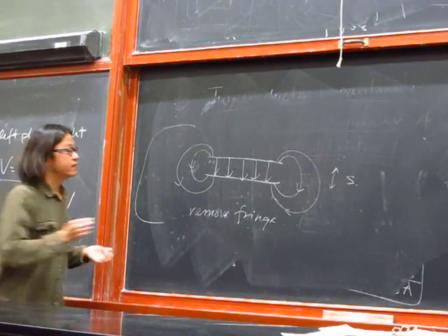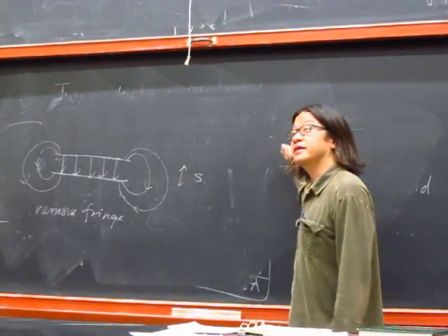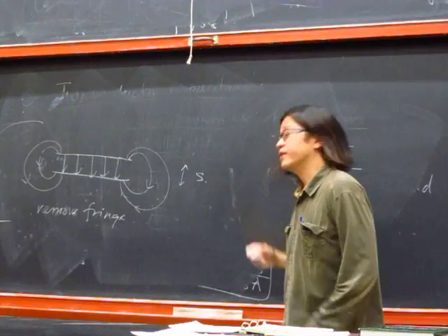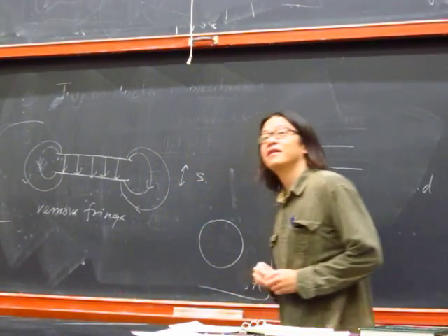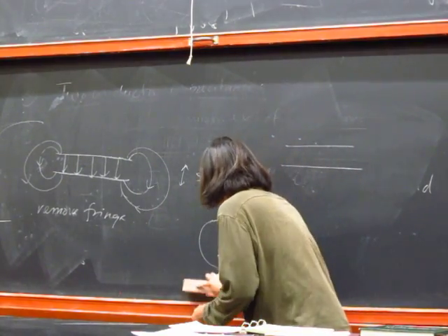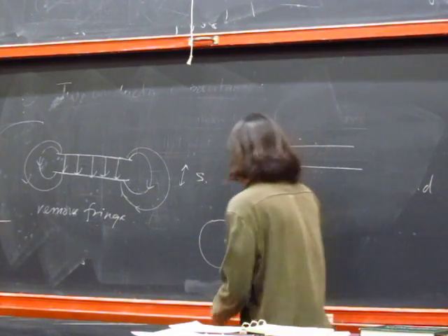So how do you do that? The way you do that is you actually encapsulate this capacitor inside another capacitor. If I draw it from the top, suppose this capacitor looks like a circle. There is a lot of fringe effect on the side, so I build this capacitor differently.